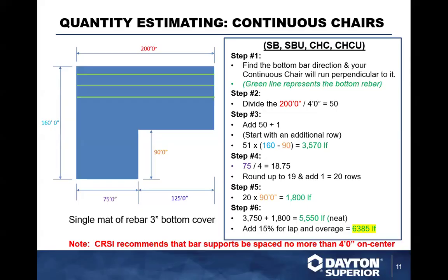Things you want to take into consideration are bar supports, especially in a bridge project, where you may end up changing rebar sizes halfway through the pour. Especially in tension zones on bridge structures, they have a tendency to upgrade the rebar strength.